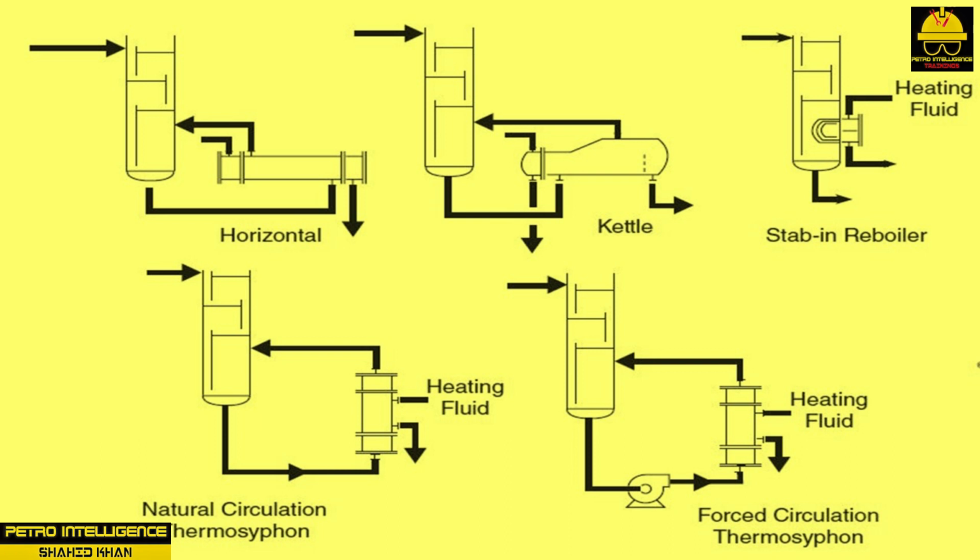Bottoms products typically contain the heavier components from the column. Reboilers suction off the bottoms product and pump it through their system. Product flow enters the bottom shell side of a reboiler. As flow enters the reboiler, it comes into contact with the tubular bundle. The tube bundle typically has steam flowing through it.